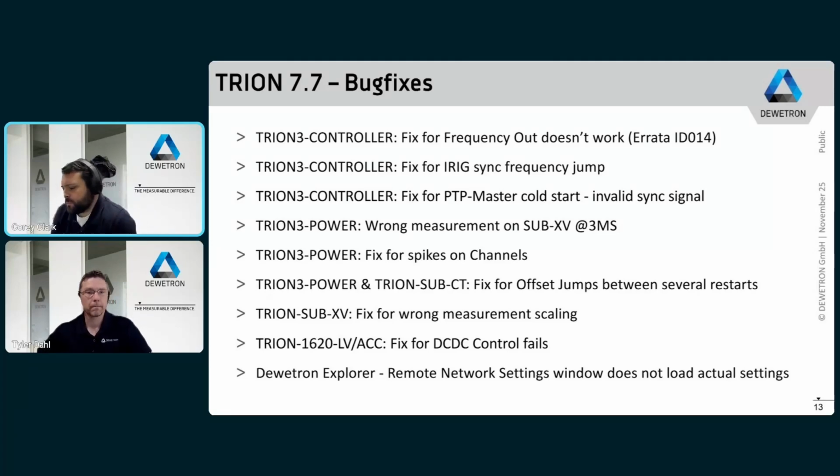And then the DEWETRON Explorer itself. The DEWETRON Explorer is that second software package I've already mentioned to jump into for your firmware updates and status checks of your hardware. In that software, you can set up your network settings for your TRIONET devices, so TRIONET and TRIONET3. In there, you can set static IP addresses and subnet mask information for your TRIONET devices through the network settings window.